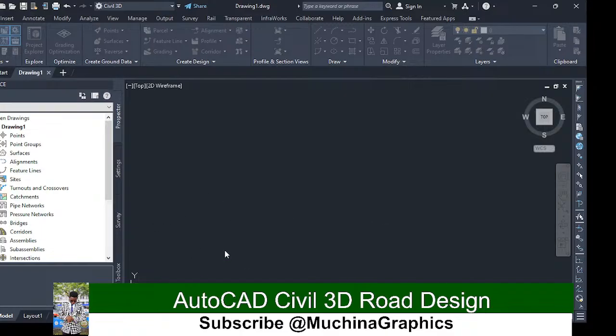These points are in CSV format, then I can open them. So when I open them, I will just change the point file format to PNEZD, point number, northings, eastings, elevation, and description. Then I click OK.